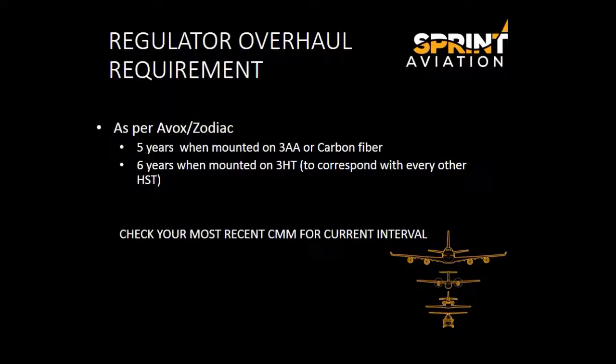When mounted on a 3AA or carbon fiber cylinder, the regulator overhaul interval is 5 years. When mounted on a 3HT cylinder, this interval goes to 6 years to correspond with every other HST activity. Always check your most recent component maintenance manual for current intervals.